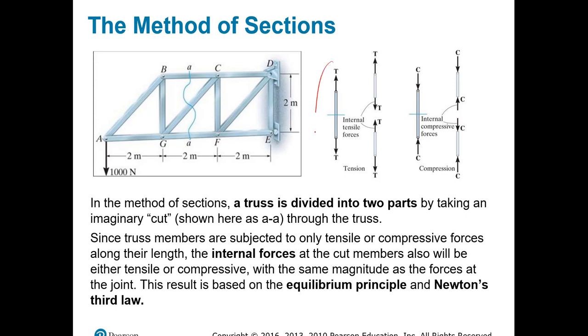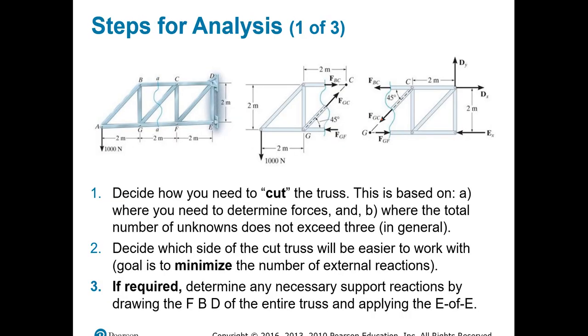So basically, if you have a member and you break the member in half, you can break it into two parts, but don't forget the internal reaction that will be created because of that cut that you place. And that could be compression or tension.